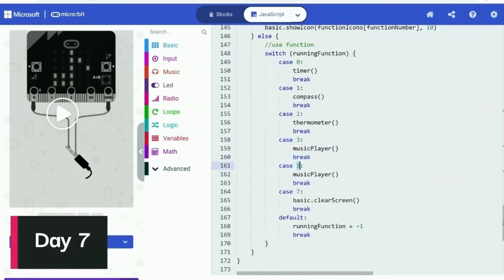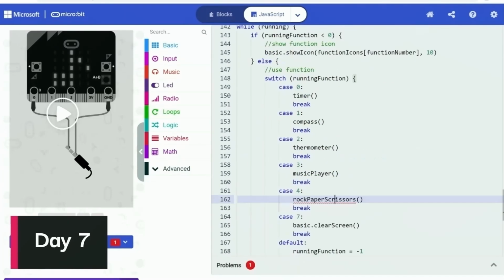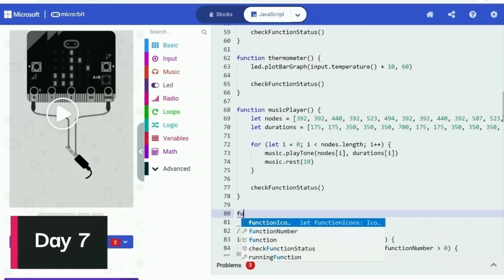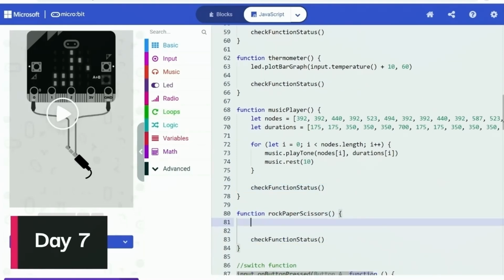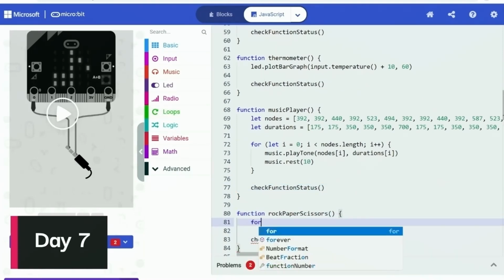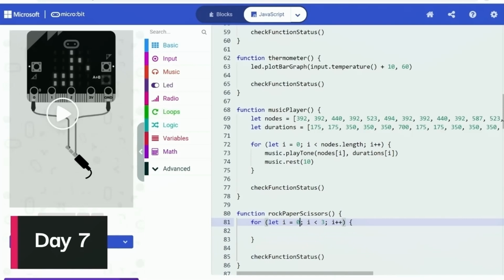Basically I put music as the name of the function, which apparently is also the name of the namespace for Microbit's music functions. And that's what made the code fail to compile. Now that all of this was solved, I got to work on something else.